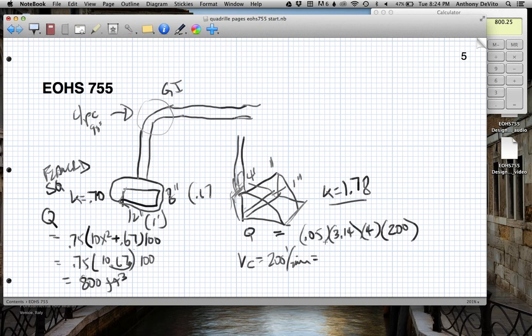So now the amount of air we're going to move here is going to be 0.05 times 3. I think VC is going to be the velocity at the slot, which is 1500. I think that's why they're giving us the slot velocity. They're giving us the length, but they're not telling us the size of the slot. Oh no, we have a distance x.